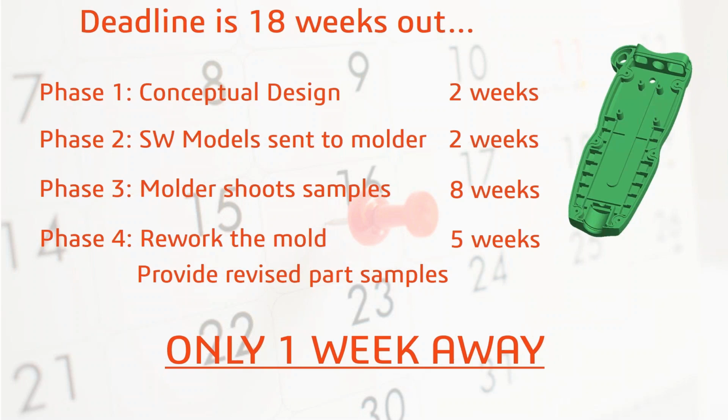When you do have a problem, and fortunately for me, I only had those small problems of sink marks. I can't imagine the problems I would have had if it was short shotting, if it was having gas traps or burn marks, or if the balanced runners didn't work out. There were a million other problems I could have experienced. I got lucky. Otherwise, I would have been in real trouble.